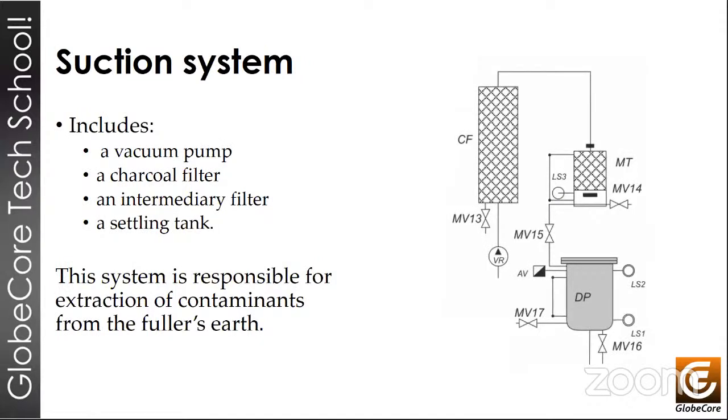What it does, it pulls air or circulates air through the Fuller's earth columns. It has 2 fundamental functions or purposes. First, it is used to increase the temperature during reactivation because of the constant passage of air in conjunction with the temperature that the heater creates, ensures the full ignition of Fuller's earth that burns out all of the captured pollutants. And with the constant air circulation, the fire, that burning, spreads through the columns evenly.